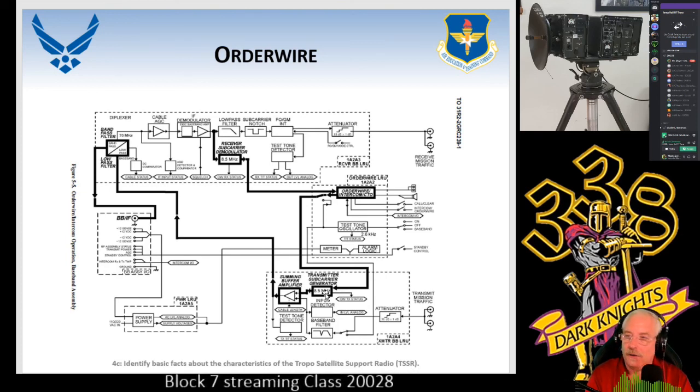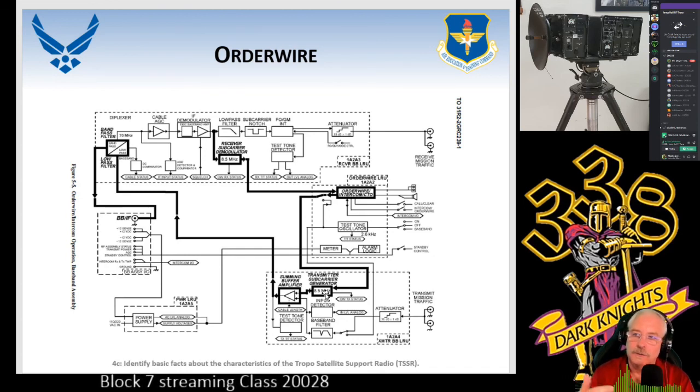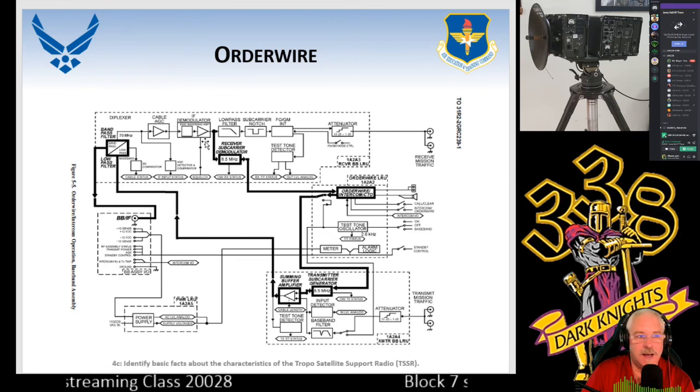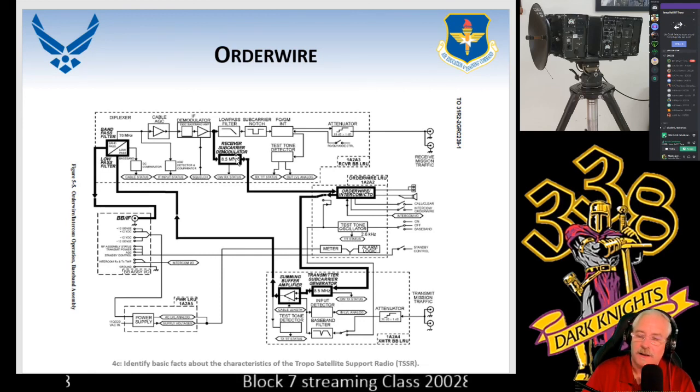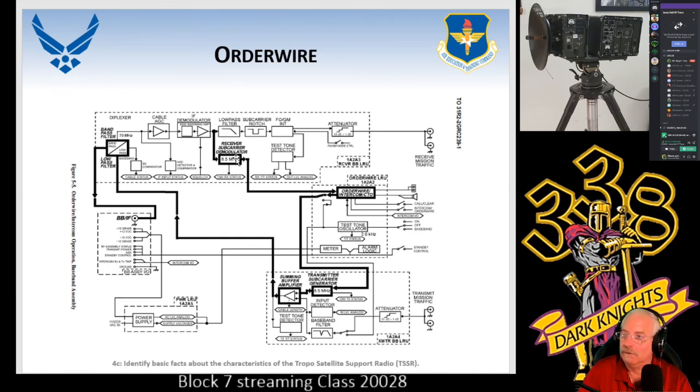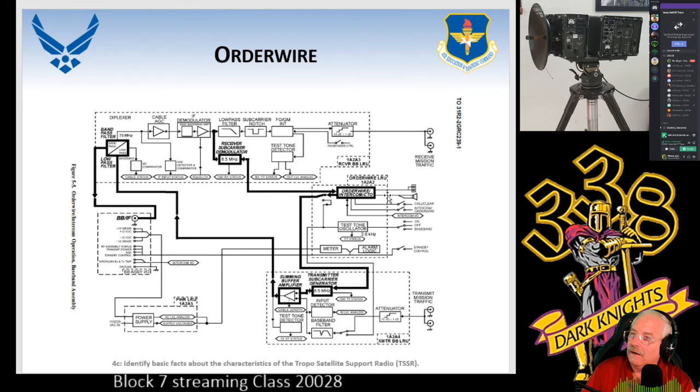Now, when you come out of the RF assembly, for example, if the distant end is talking to you, you're going to hear it, and the way you're going to hear it is, remember this IF demodulator up here, top left-hand side next to the cable AGC? You look at the bold line, and it's going to come down, and it will not use the aggregate. It will only demodulate the FM carrier. It looks at that aggregate and goes, what do you want me to do? It basically blocks it there. So when it comes down this line, this is what you're going to hear on your handset.